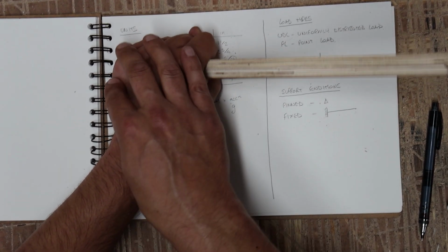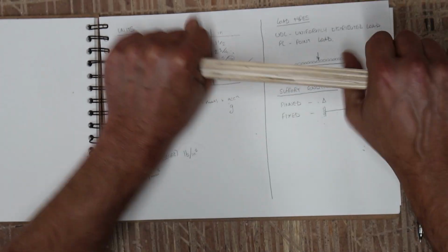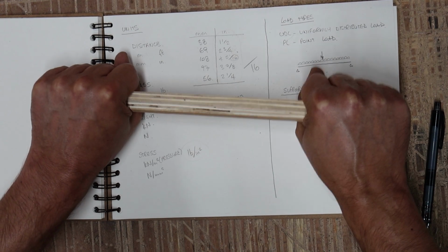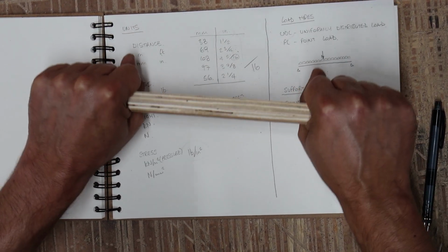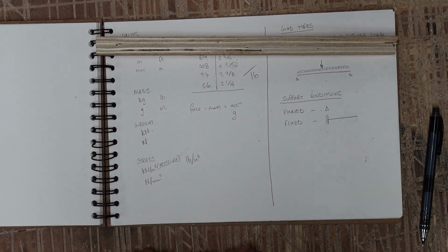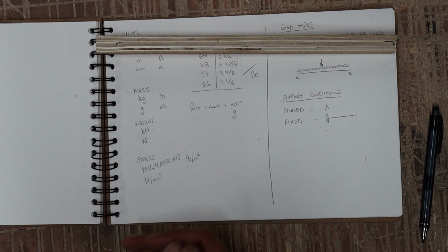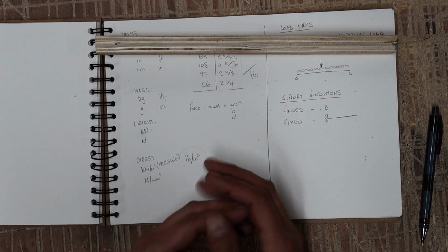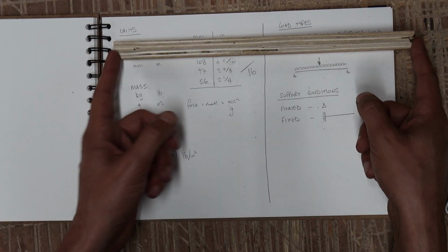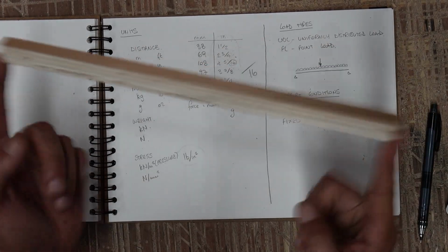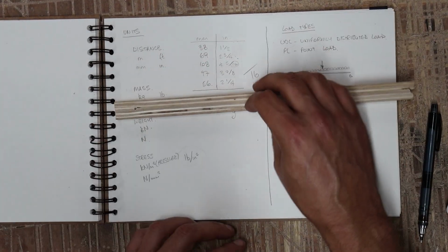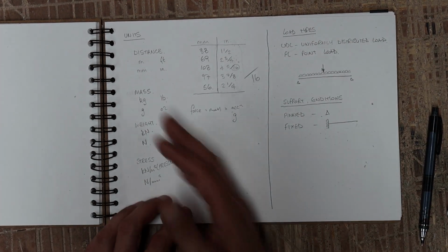The only time we really use it is for these cantilevers. We can do beams with fixed supports at both ends, which we'd call a built-in beam, but it would cause so much work on the rest of the structure that it's easier to just assume it's pinned. That's how it works in engineering. We're so afraid of these mechanisms that we'll go overboard and try to keep things simple. If we assume pin supports, then it has no real action on the rest of the structure. I'm getting too technical. Let's forget I talked about that, because it's not relevant here.